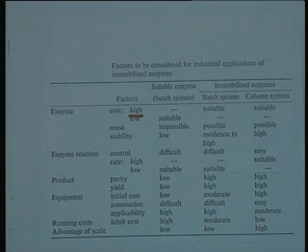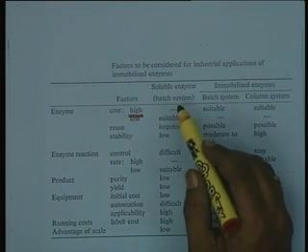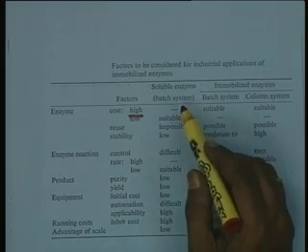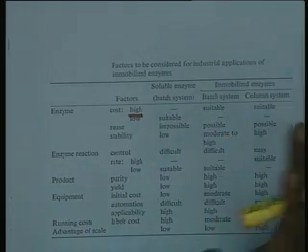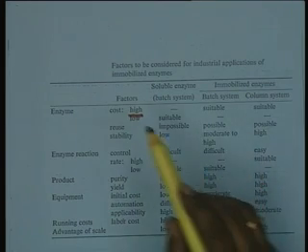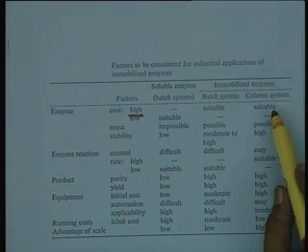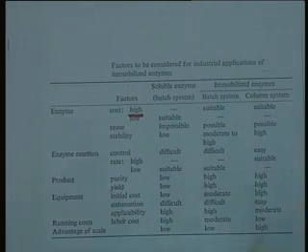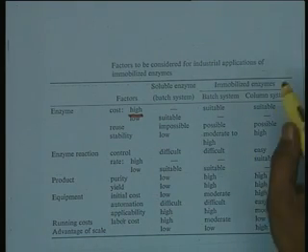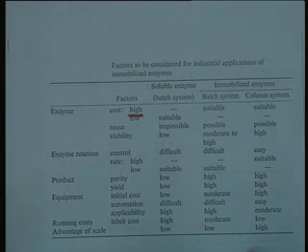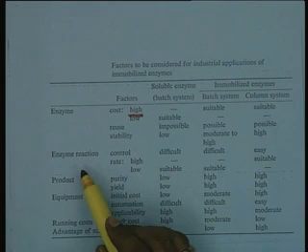And in fact, I would like to tell you that an enzyme like alpha amylase, which is one of the examples of one of the lowest cost enzymes, is essentially used in a soluble form in a batch reactor, because you can afford to discard it, you need not recover it, whereas high value enzymes are most suitable to be used in the immobilized form. And of course, when I say column system, I am covering both either a packed bed or, depending on the process, a CSTR also, but of course here the column gives only a column.